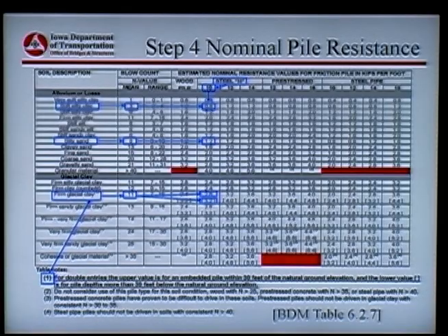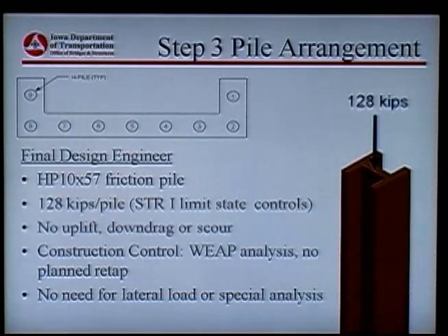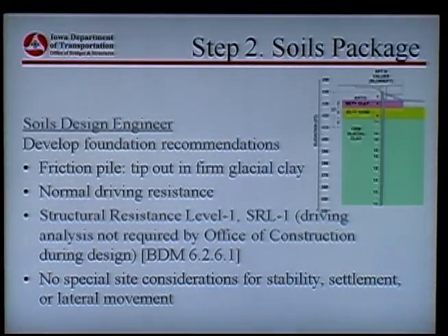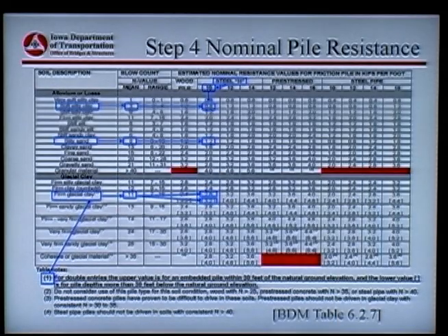So what happens here is we had a soft silty clay at the top, then a silty sand, and then a till below. If we just go back, there it is right there. So we had the soft clay at the top right in here, with the pink, the sand is in the yellow, and the till here is in white. For the soft silty clay, it was soft, and we come down from the steel H-piling HP10s, and we're getting this 0.8.